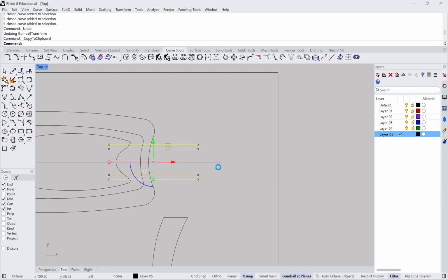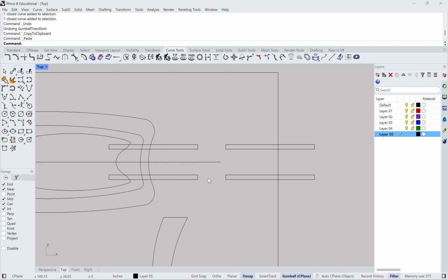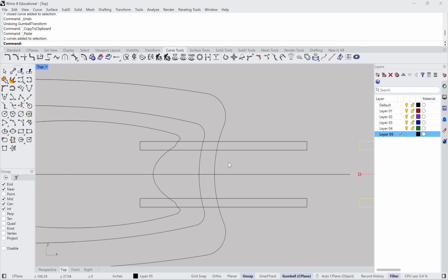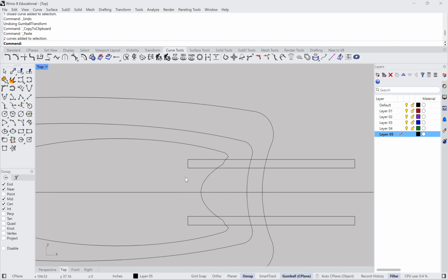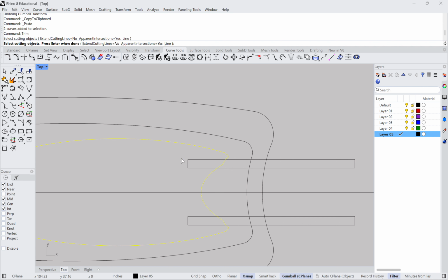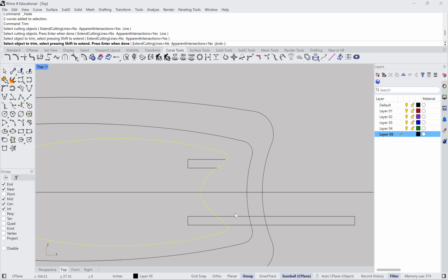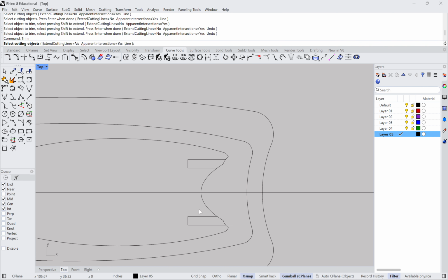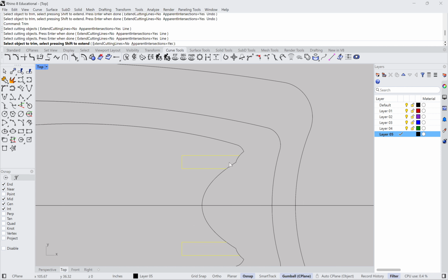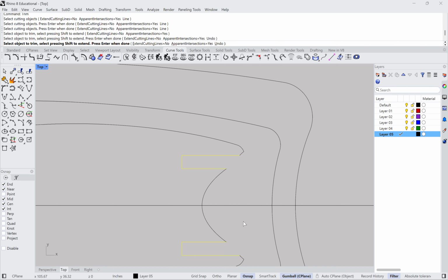So I'm going to make a copy and then move the other copy 5 inches away. That way, I know I moved these 5 inches here. So if I do a trimming operation with this smaller shape here, I'll use the shape to trim away this part and this part, retrim, except now I'm using these to trim away these parts.